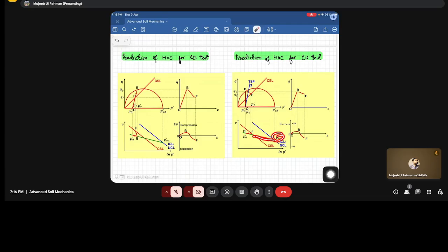This is the unloading line, and from this point O, our stress path will move straight, because if we talk about the elastic response, it goes till it reaches the yield surface line. Fine. So O B dash will be the same point here. Once it reaches the yield surface line, it will start to yield to reach the critical surface. Now from here to here, it will be a kind of yield.